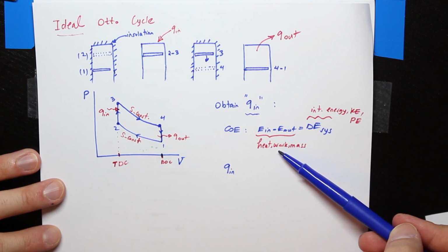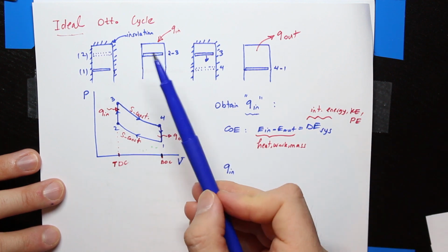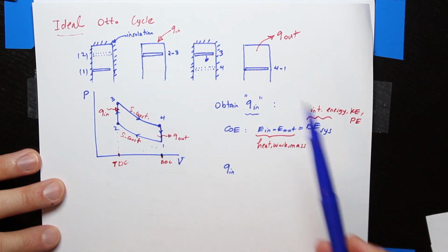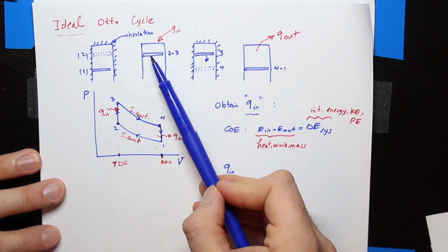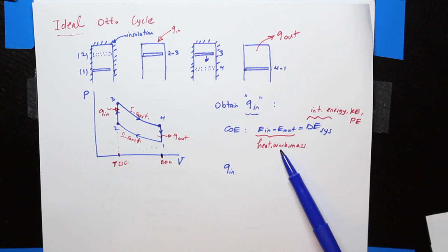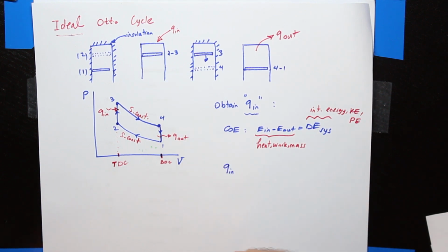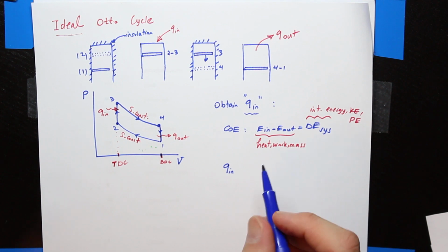It has electrical work, mechanical work, boundary work. If that is a boundary work, there should be a change in the boundary, or PdV, let's say. But the boundary doesn't really move, so no boundary work. No electrical work. You do not see any electrical resistance here. No mechanical work as well, because you do not see any paddle wheel, for instance. So we do not have work at all on the left hand side.